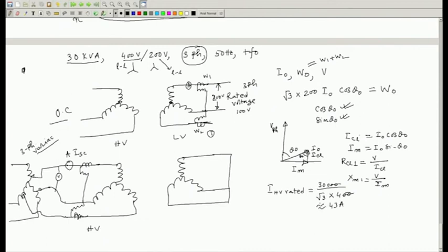So, you have to choose an ammeter which can read 50 ampere, say, and similarly the wattmeter current coil, but the line to line voltmeter rating should be very small, maybe 5-10% of 400 volt. 5% of 400 volt is only 20 volt. Voltage required will be pretty small. So, that rated current will be circulated. Secondary will also carry rated current like primary. So, that copper loss will be there.